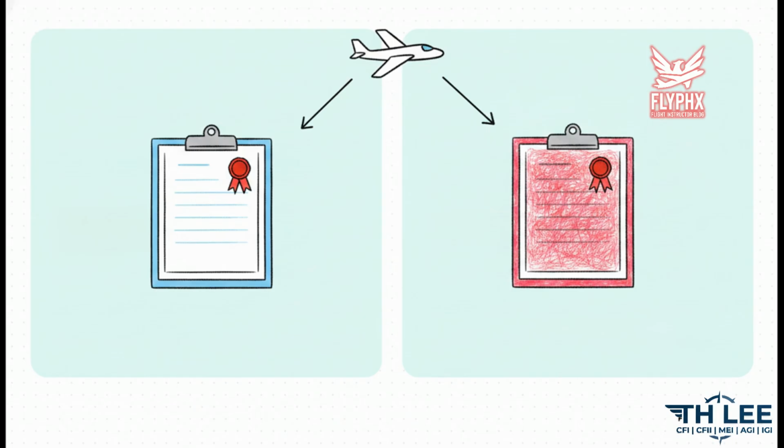So how does all this legal paperwork actually translate to your daily flight operations? Well, during your required pre-flight conformity inspection, you absolutely must locate the airworthiness certificate on board. And I want you to notice the stark visual difference between the white and pink certificates we're looking at here. Standard airworthiness certificates, the ones printed on crisp white paper, are issued for your normal, utility, acrobatic, commuter, and transport category aircraft. On the flip side, special airworthiness certificates are printed on pink paper. These are strictly reserved for primary, restricted, limited, light sport, or experimental aircraft.